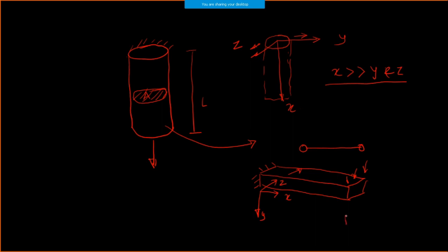That's why this 3D model is converted into only a 2D model, and we assume that the deformation happening in the z direction is the same in any of the planes, may be one plane, two plane, three plane. All the planes are the same. That's what we have studied as a plane stress condition. In a similar fashion we have a plane strain condition, and similarly an axisymmetric condition. So that's what we have converted.